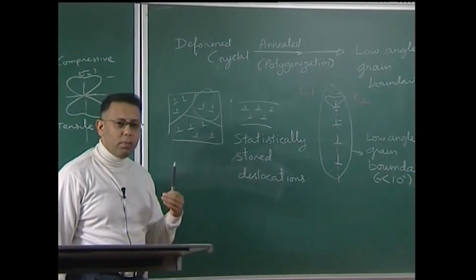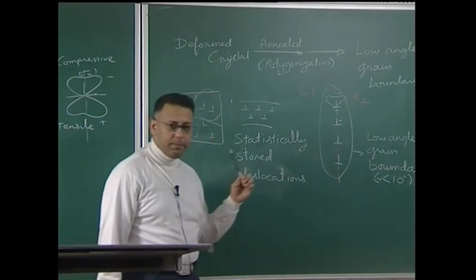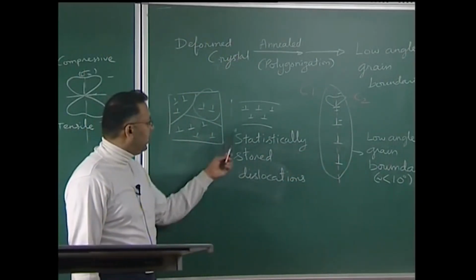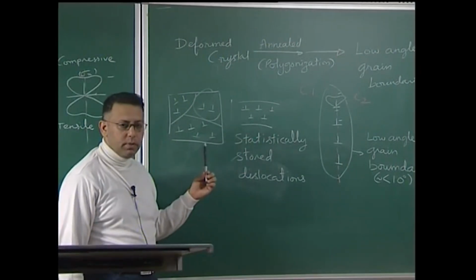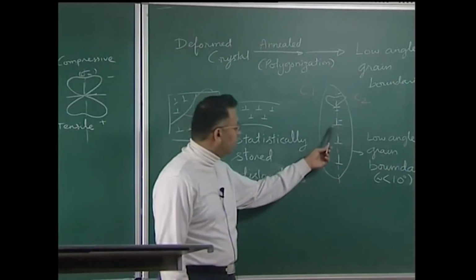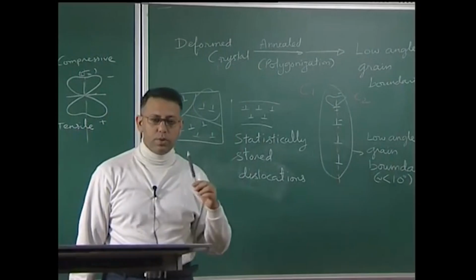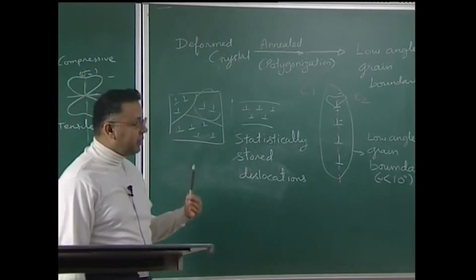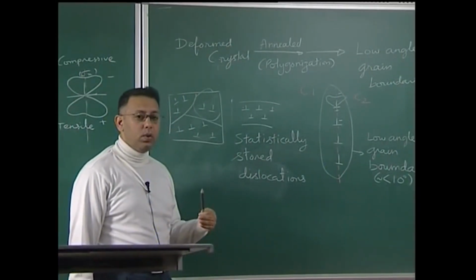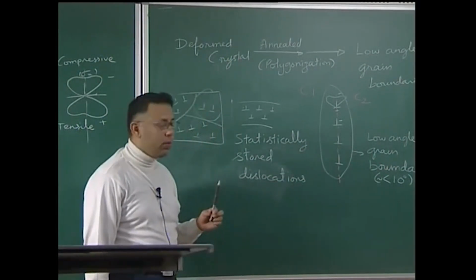Now, suppose I try to plastically deform this specimen vis-a-vis this specimen. It is clear that these dislocations are free to move because they play no structural role in the material. On the other hand, if this dislocation leaves this boundary, then the misorientation angle is going to change, and therefore it is energetically not feasible, or not that easy, to drive a dislocation away from this boundary.